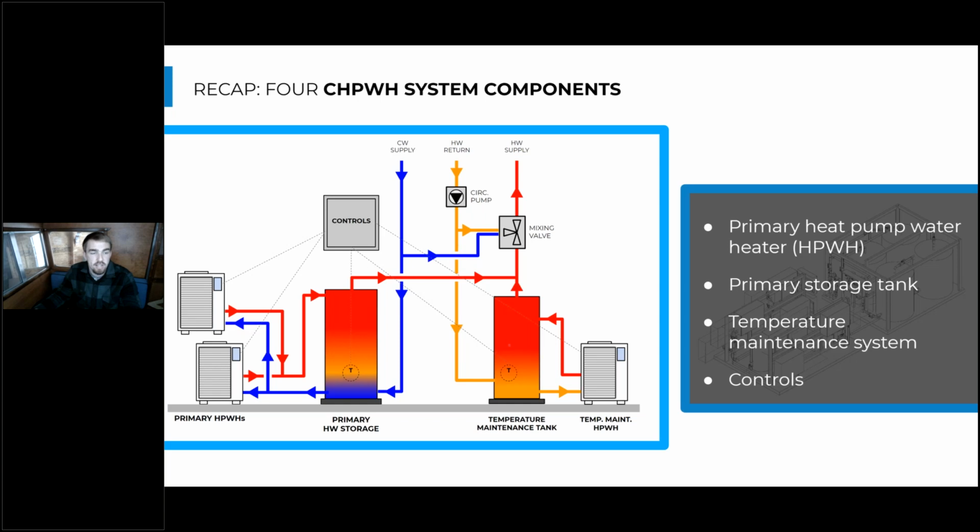And the reason it's doing that is because as it passes through this tank at a really high temperature, it's actually warming up all the water around it. So with sufficient hot water usage, your hot water circulation loop is actually being reheated by that primary hot water, rather than needing to have a heater to heat it completely separately in a less efficient manner.